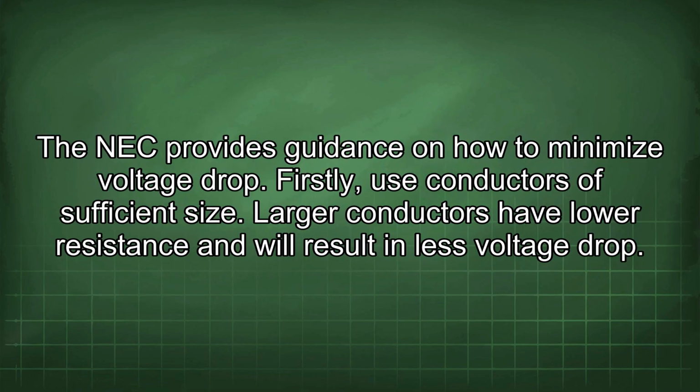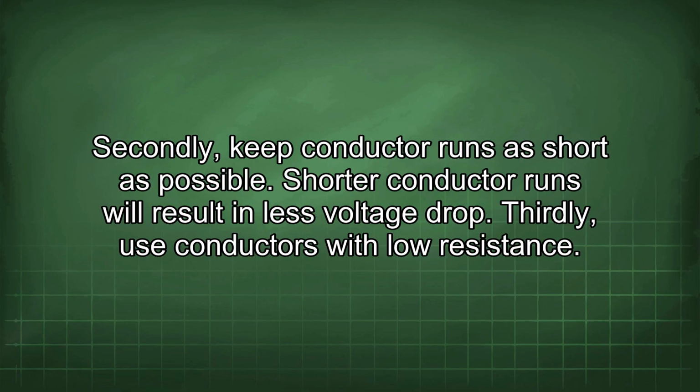The NEC provides guidance on how to minimize voltage drop. Firstly, use conductors of sufficient size. Larger conductors have lower resistance and will result in less voltage drop. Secondly, keep conductor runs as short as possible. Shorter conductor runs will result in less voltage drop.